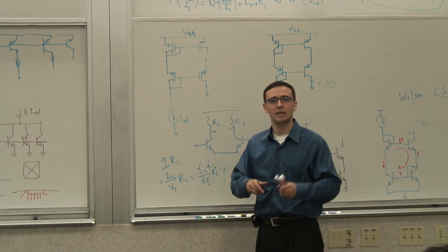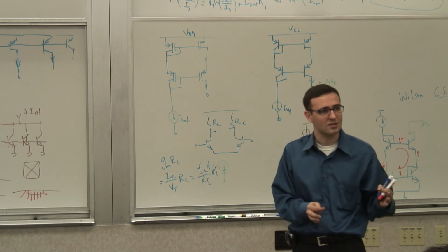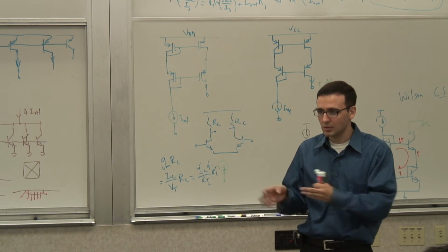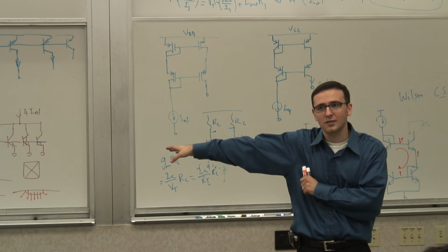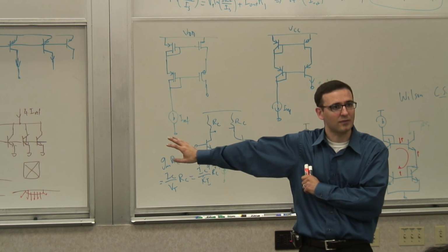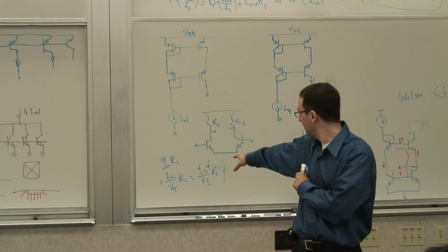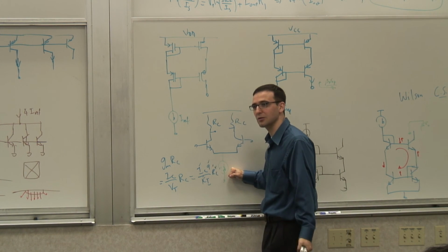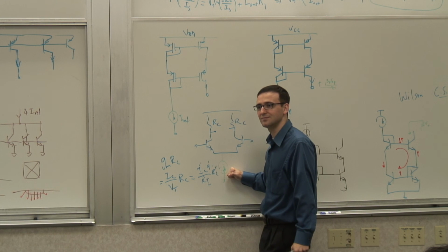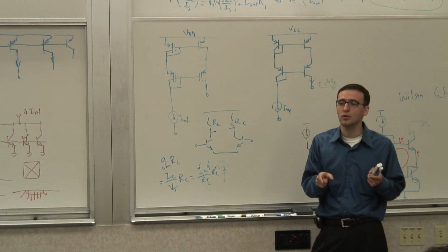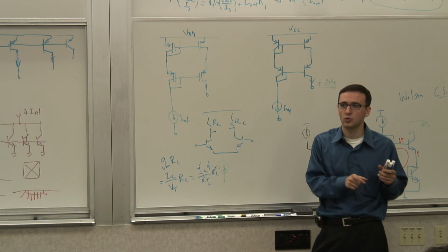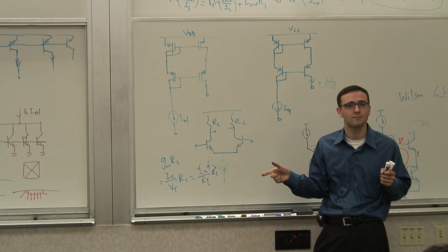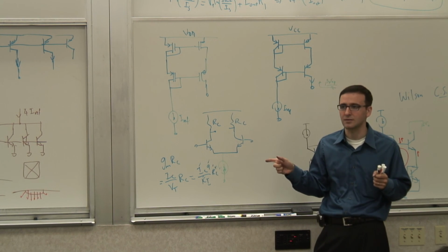Depending on the situation, we'll see that for MOSFETs it's different, and for different situations it's different. So we'll talk about how we generate all these different kinds of currents that have different temperature dependence, and why we do them. But I want you to keep in mind that just the fact that this kind of current is absolutely constant doesn't mean it's a good thing. If you want to keep gm constant in bipolars, you need PTAT, proportional to absolute temperature. Correct. Or a VT reference.